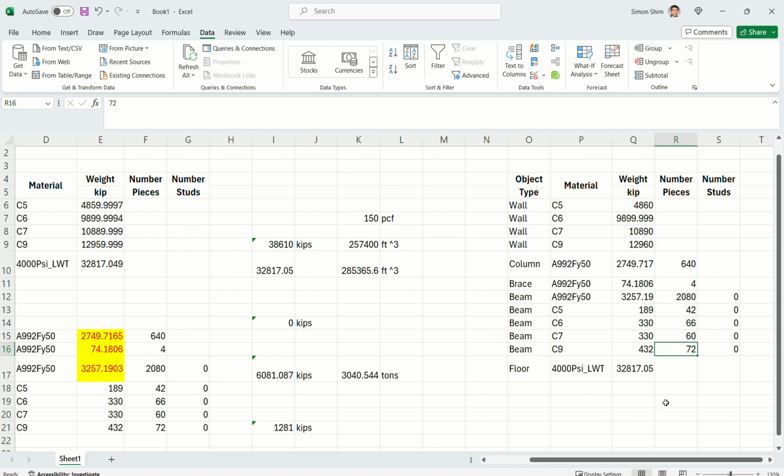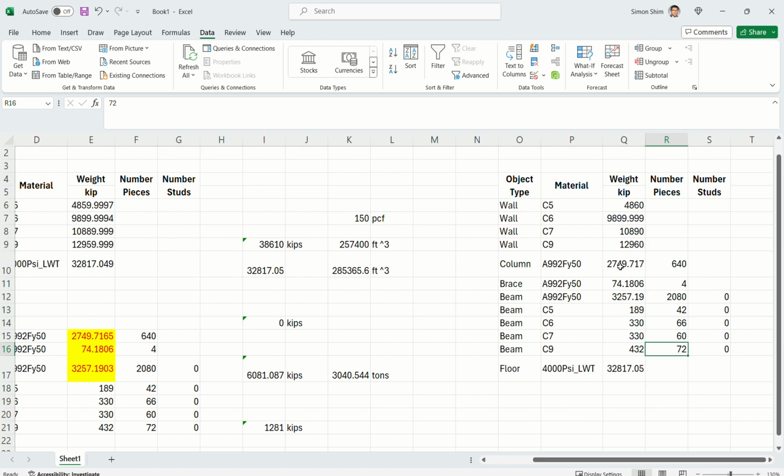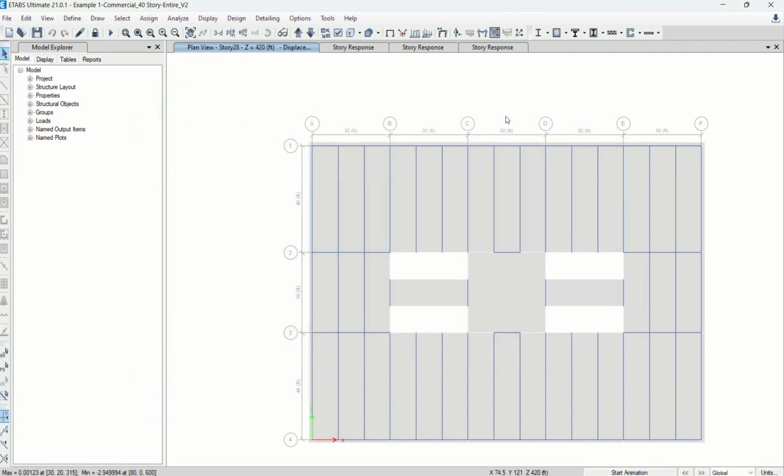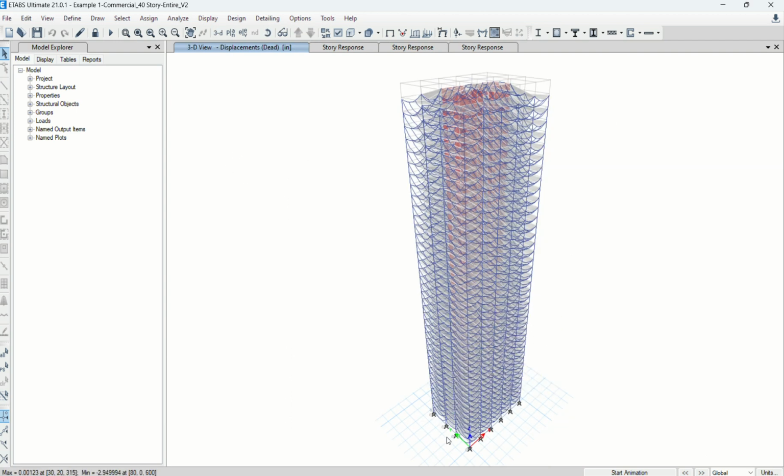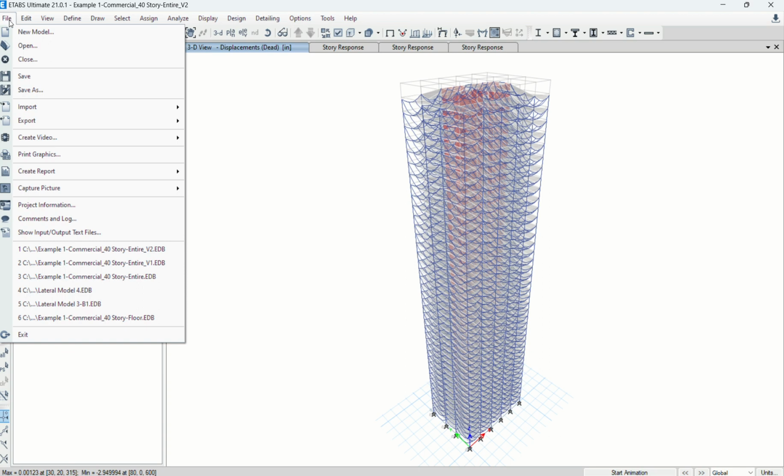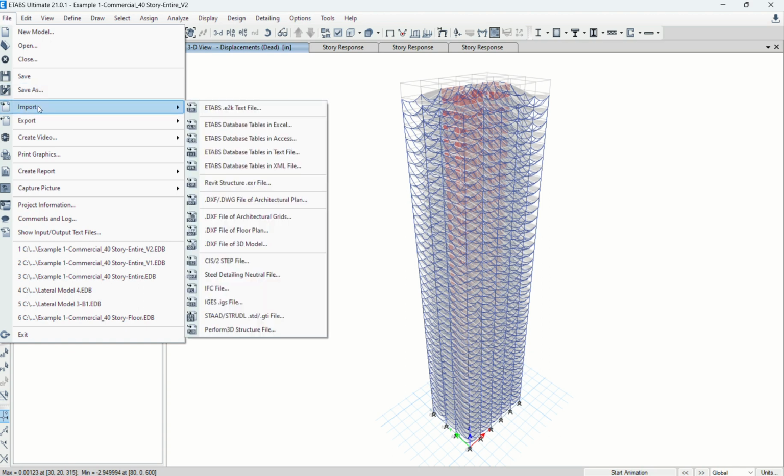Okay, so this is something like summations. The wall and beam, you could sum them all up, right? You could just calculate the total weight of the wall and beam, divide by the concrete density, and get the volume. All right. Since we just talked about the material takeoff, now, since this model is ready, we're going to transfer all the data, the column and wall reactions, from this model in order to create the foundation model, right?